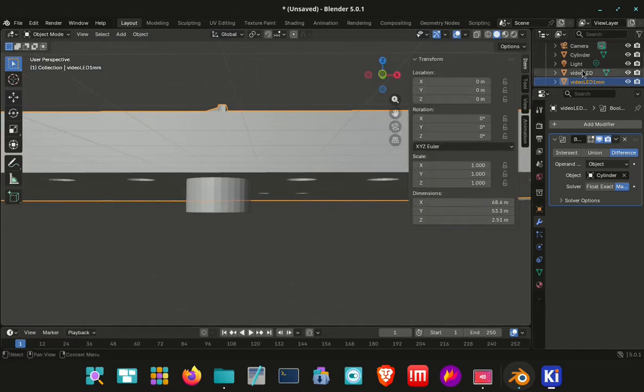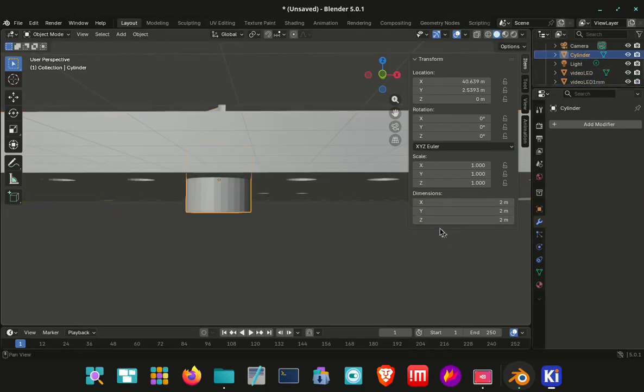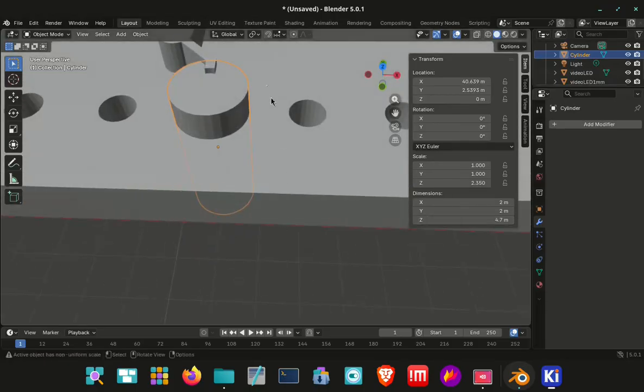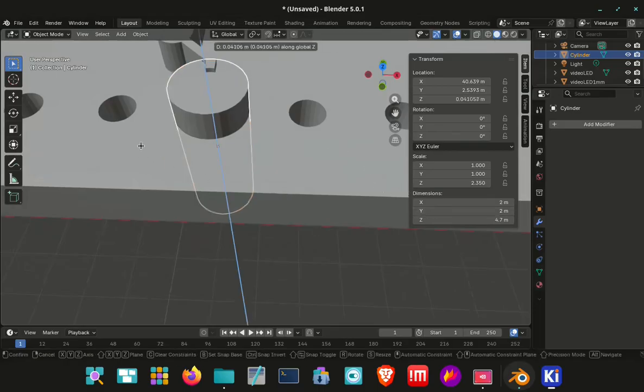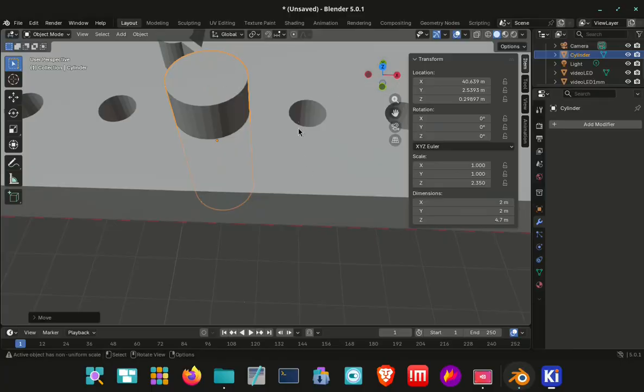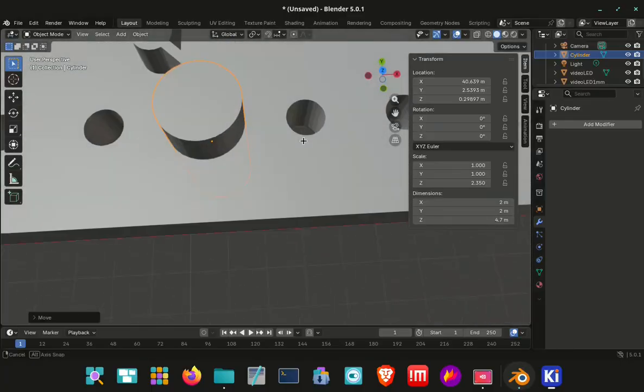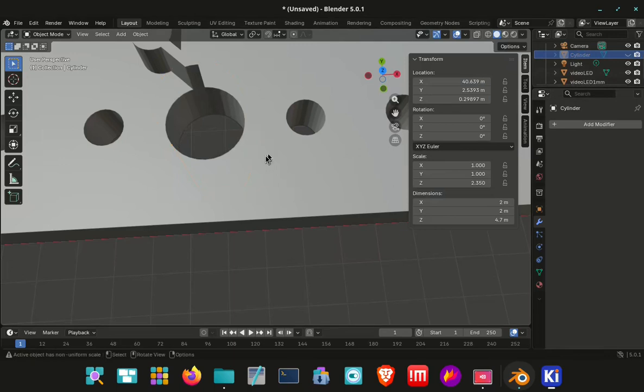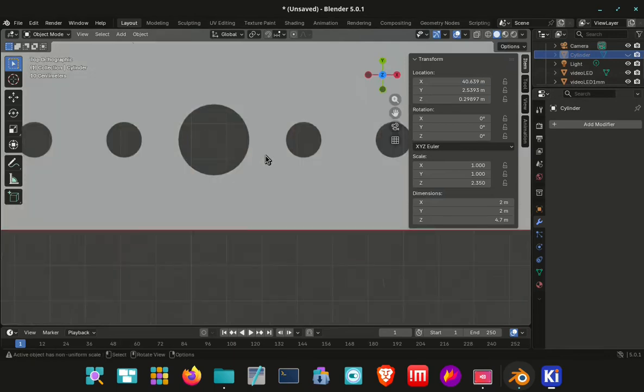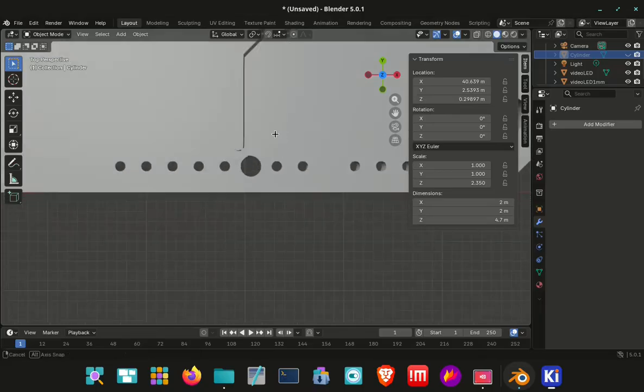Right, so with the cylinder selected, we want, which one is it? Is it Z? There we are. That'll do. It doesn't have to be perfect. It's only to make a hole. GZ, so it comes up and it covers that, because you want the hole to go the whole way through, don't you? Because you've got to put pins through. Okie dokie. Now, if I make the cylinder invisible, there we go. We now have a 2mm hole. That is going to be perfect for our components.